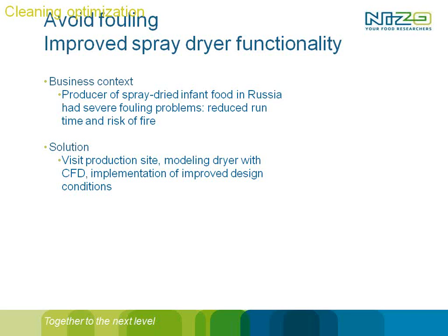Fouling can result in smoldering, so you can have lumps within your spray dryer which start to smolder, and the smoldering can result in explosion risks. So you should avoid fouling in the spray dryer.